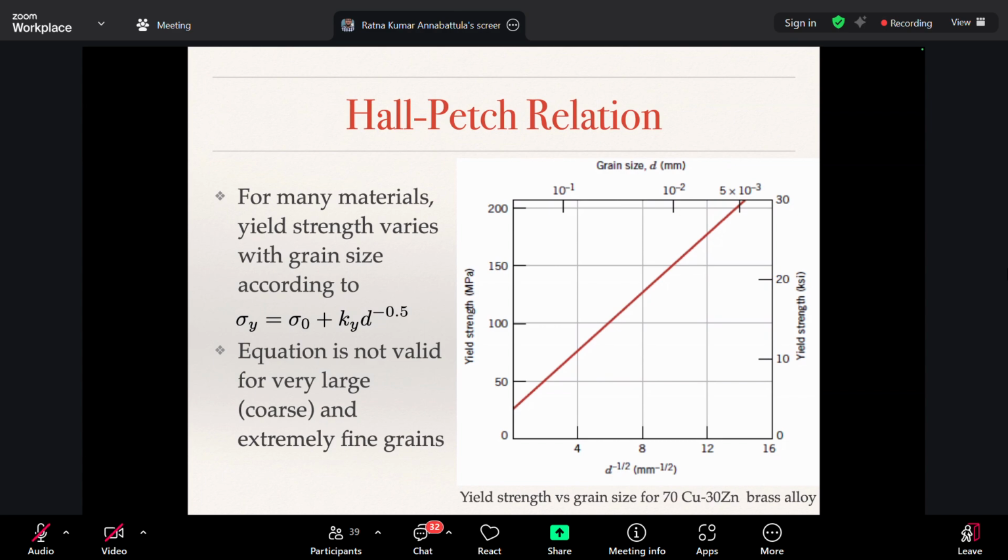And each nucleus starts becoming a solid locally, and that is how you will have different grain orientations that we have looked at in the previous class, right? Now, if you are doing extremely slow cooling, then what happens? The cooling rate is very low, so you are giving enough time for diffusion to take place, isn't it?